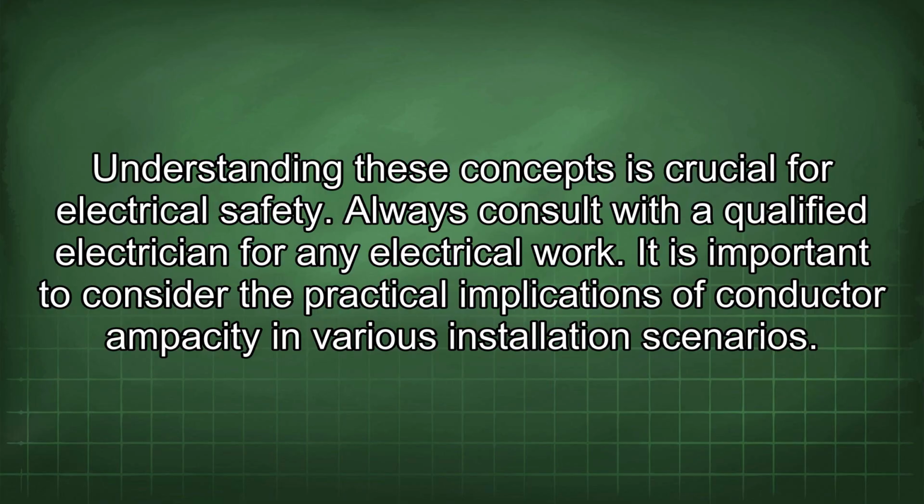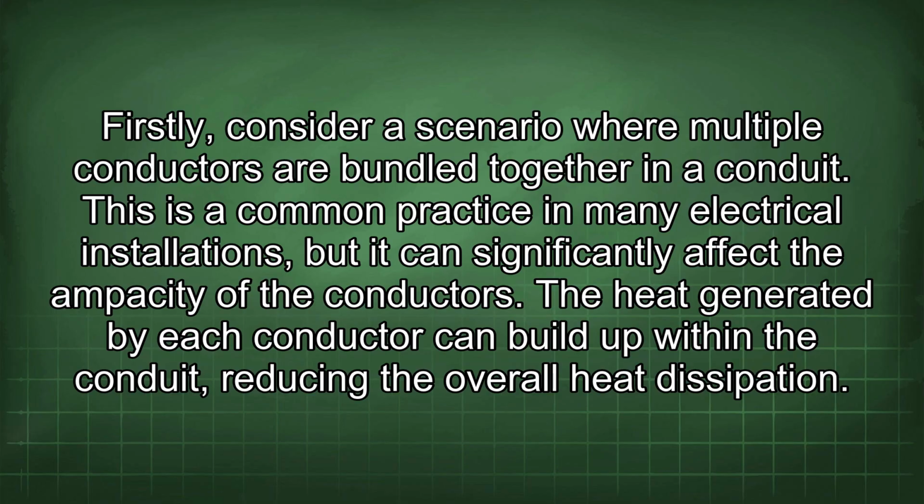It is important to consider the practical implications of conductor ampacity in various installation scenarios. Firstly, consider a scenario where multiple conductors are bundled together in a conduit. This is a common practice in many electrical installations, but it can significantly affect the ampacity of the conductors.